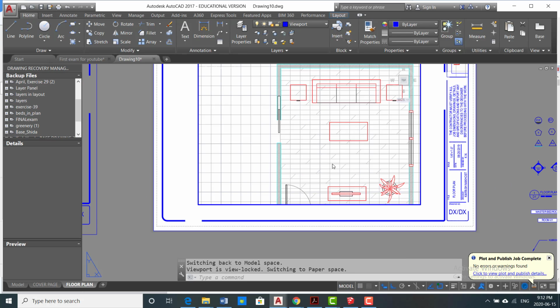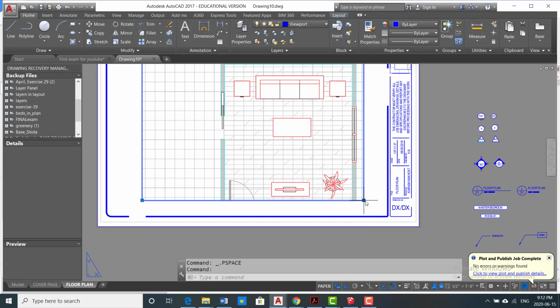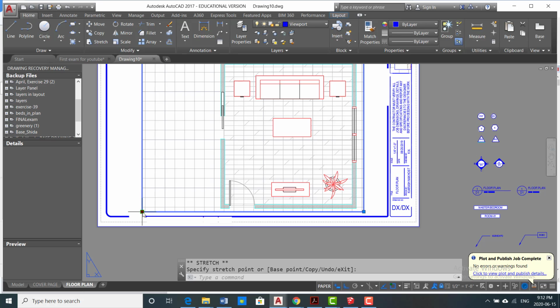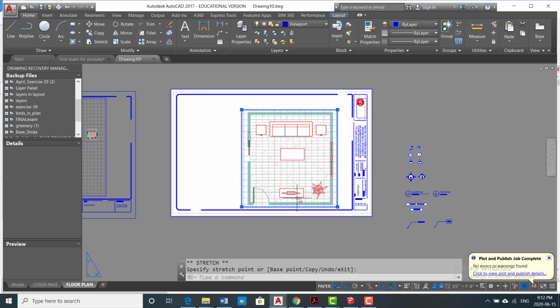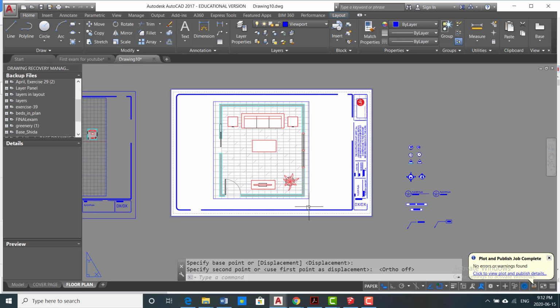Then to modify it, it's pretty simple. See, I am missing some part of my drawing. Just deactivate your drawing, click on the border, and see, just make it a little bit bigger. Grab the handle, maybe make it a little bit smaller this way. Then I can use move. See, while it's activated, or you start a move command, select the border, and you can just move it like any other object in AutoCAD. Maybe I place it here.